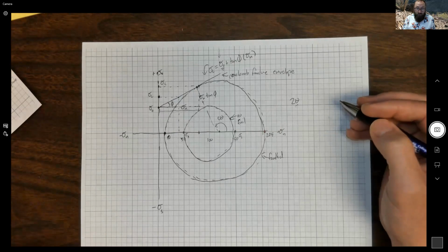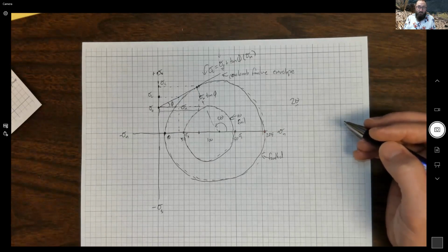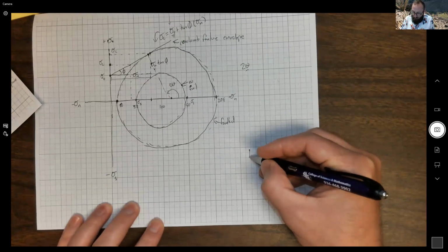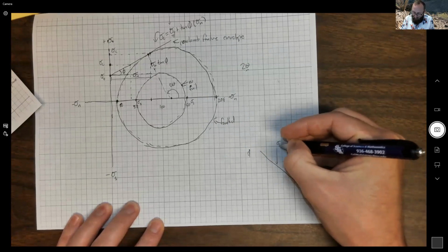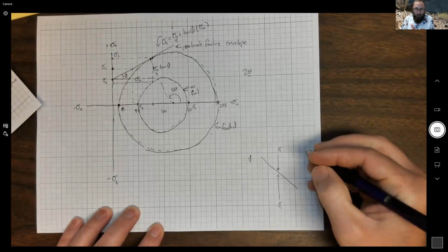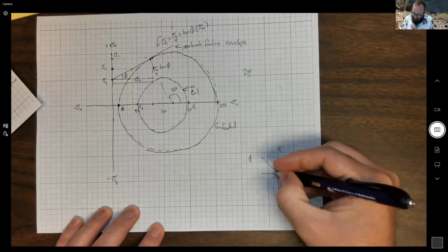And so what we learn is that the differential stress level in a fault is greatly influenced by phi, the internal angle of friction, and that the internal angle of friction, phi, determines theta, which is the angle between the direction of greatest principal stress, sigma 1, and the normal to the plane. We can think about it just on a simple diagram. Here's sigma 1, sigma 1, and sigma 3, sigma 3.